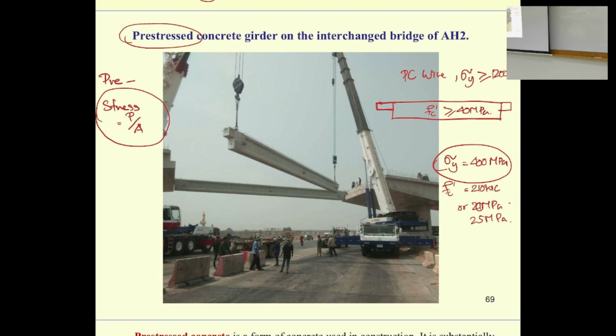It's okay. So basically, if this one is a normal steel, right? If we put some load over here, like the normal steel means the normal beam, the normal concrete, and the steel. If we put it here like this, it's going to deform a little bit. Which means that's why we put some allowable deformation equal to L divided by 360, to not let the beam deform until it provides some stress to the brick. And L divided by 240 for the roofing beam.